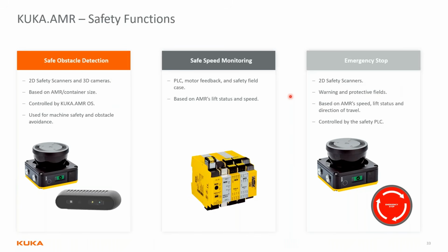First, before we have the AMR moving, we have a remote controller that we plug into the AMR. We drive it around in your environment, and it's going to create a map. Based on that map, the AMR knows where it's at. So it's not GPS. We can use color lines on the floor. We can also do QR code, but our main method is SLAM.